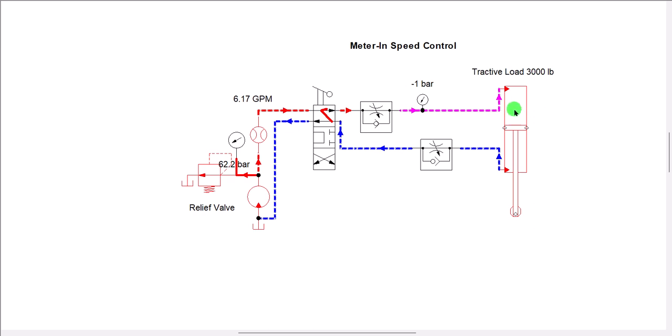This negative pressure is due to the vacuum that we momentarily create above the piston, and we must avoid the formation of such negative pressure for two reasons. First of all, the extreme low pressure above the piston may cause the liquid, whichever we are using in the fluid power system, to evaporate and cause cavitation, and cavitation can lead to physical damage of the system.